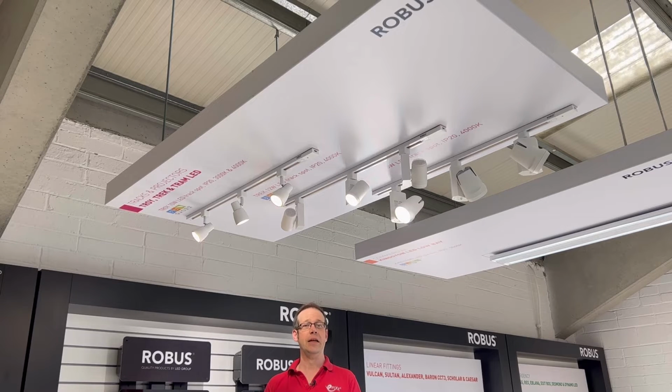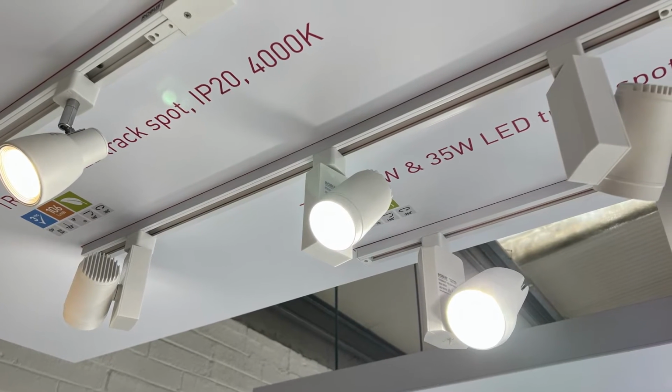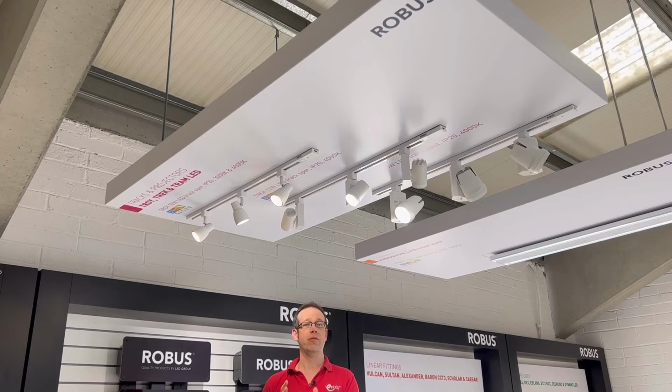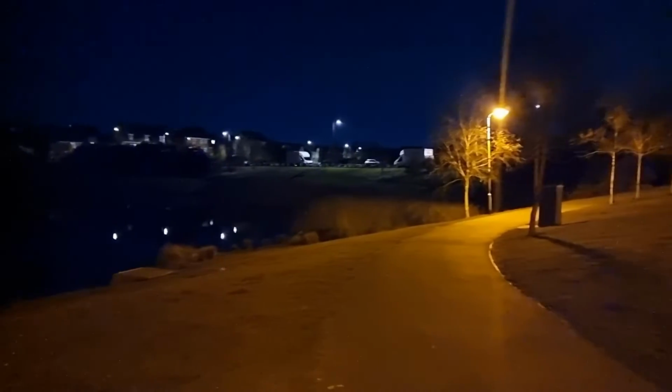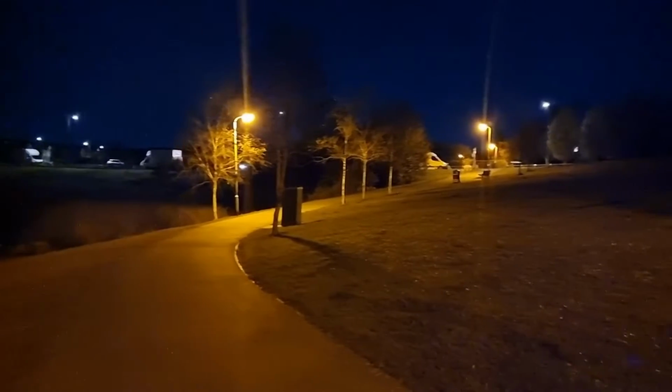When you're looking in a shop at a brand new jacket, the colours on it may seem to absolutely pop and look fantastic, so you buy it. But when you take it home and try it on in front of the mirror, it never seems to look quite as good. This is most likely because the lighting in the shop had lights with a higher colour rendering index than your lights at home, as well as a different colour temperature. Warm white sources tend to have more red wavelengths in the light they output, and cool white sources tend to have more blue. An example going the other way is the old orangey sodium lights that used to be the standard for illuminating streets and roads.